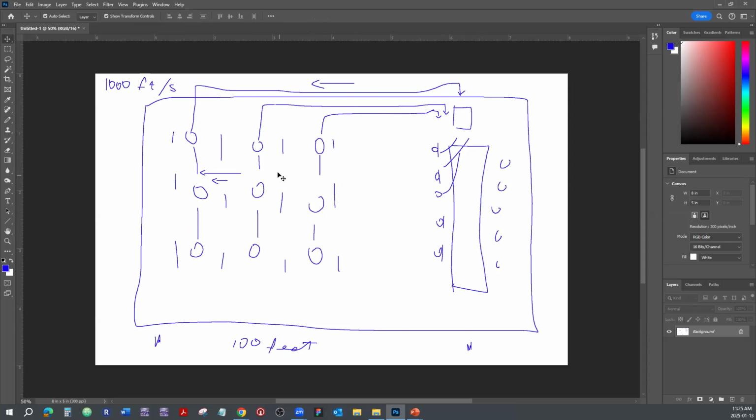In that way, you're going to time align the sound. So this line of speakers is going to wait for the sound to get from that person's mouth to this person's ear, and if you delay that just the right amount, you're going to have them hit at the same time, and it just makes a day and night difference when it comes to the reception of the sound.